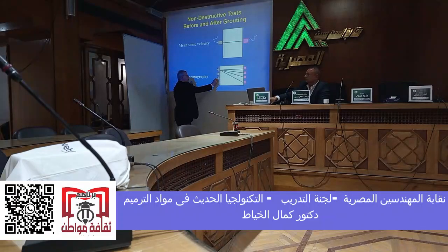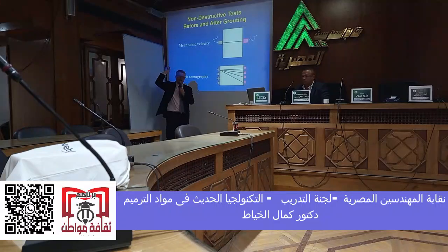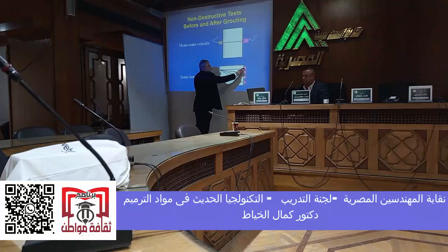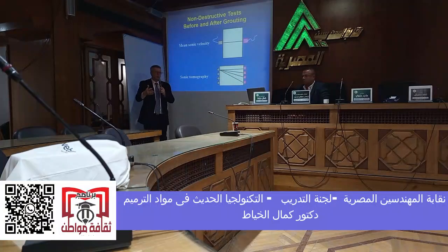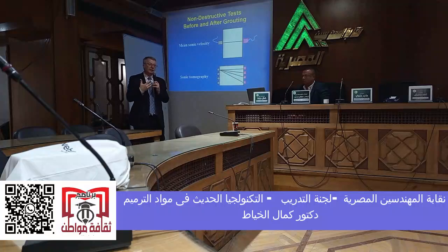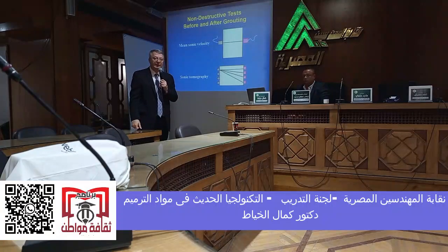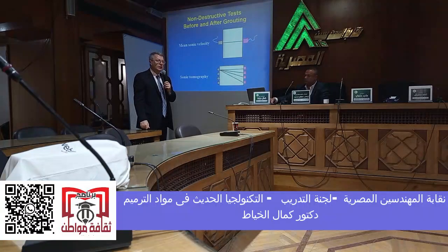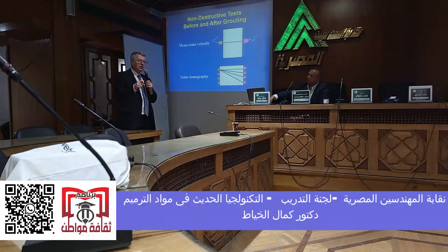They put some geofoams on one side and geofoams on the other side. The diver with a big hammer hits one of them, and they listen to the time needed to reach each of those geofoams. They do some Fourier analysis, and they determine the dynamic elastic modulus.